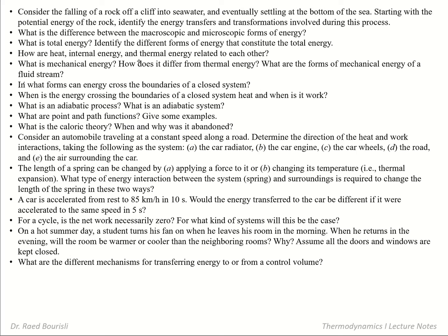That's easy. And then when is the energy crossing the boundary of a system heat, and when is it work? Well, if it's the result of a temperature difference, then it's heat. Otherwise, it's work. So compression of a gas in a piston-cylinder device increases the energy, but it is not a result of a temperature difference.